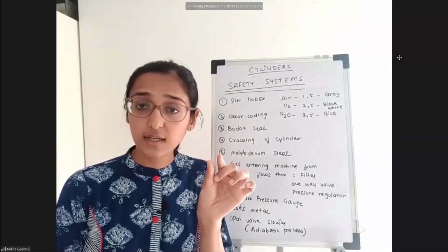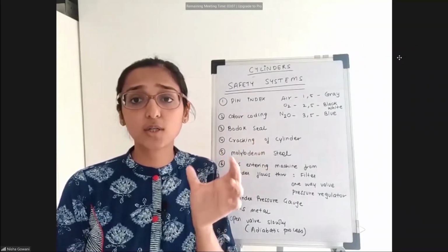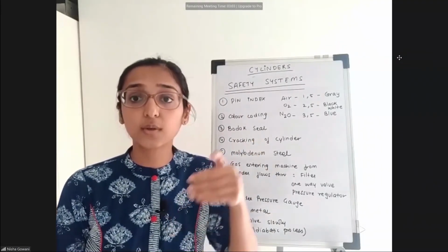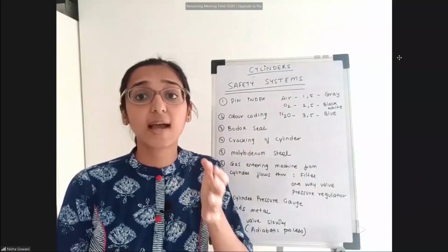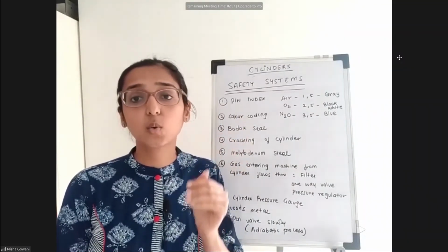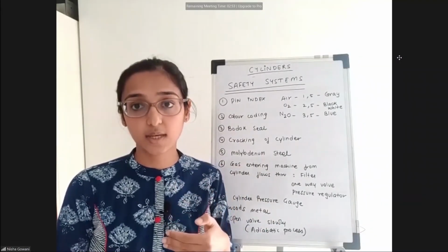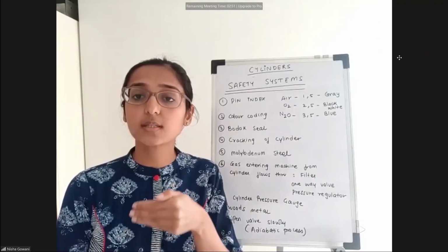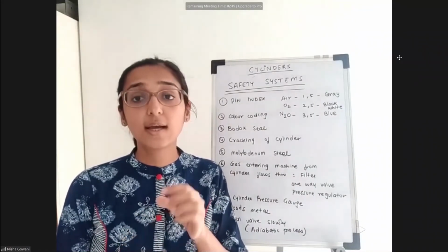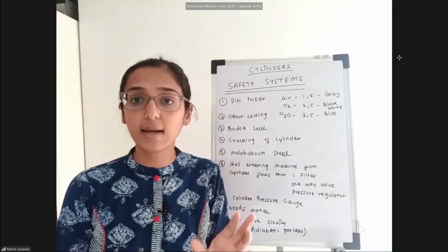The heat generated in that small space has no loss or gain of heat, because there is really no time for the heat to be dissipated. The flow of the gases is happening so fast, and the temperature rise happens so fast, that there is no time for dissipation. So this is known as the adiabatic process, the process in which neither heat is gained nor lost from the environment.